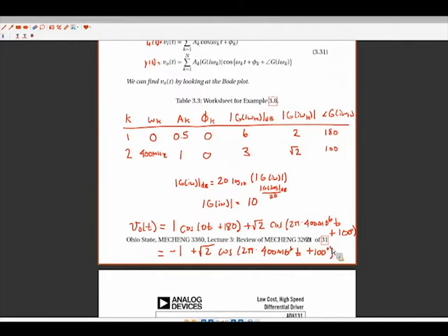Okay, so walking through what this did and how this is not behaving like the ideal function. The signal that was at 0 hertz performed in an ideal manner, right? The purpose of this was to take a signal and multiply it by -2. If we look at the DC component, it did exactly just that. The input was 0.5, output is -1, right? So it did that perfectly.